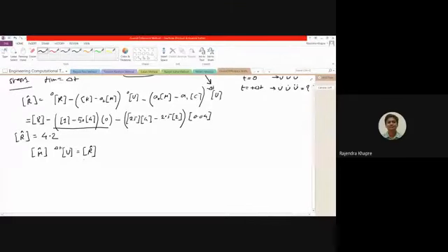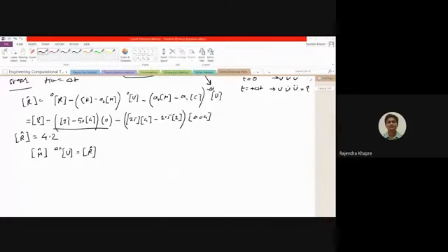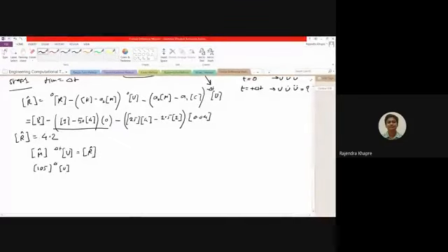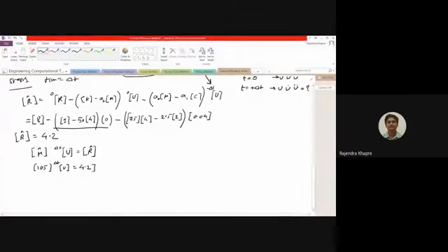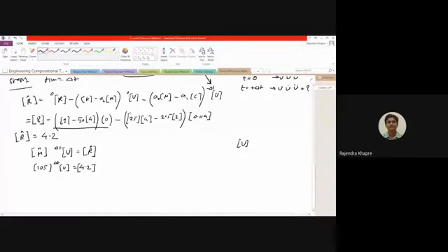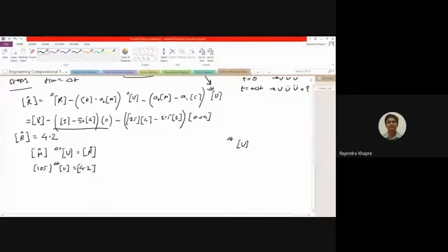Okay, so the effective mass matrix we have already calculated in the initial calculations. Its value is 105. And this is nothing but the unknown displacement at delta t, and the effective load vector R is 4.2. So now can someone tell me what is the displacement at delta t? 4.2 divided by 105. How much is that? 0.04.